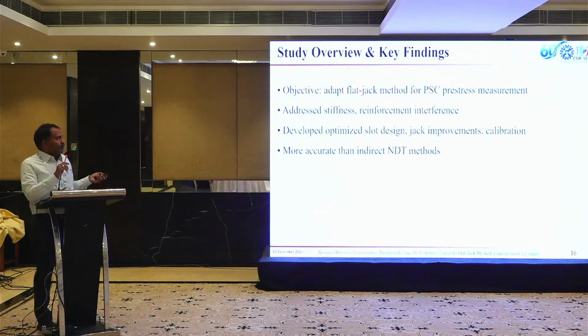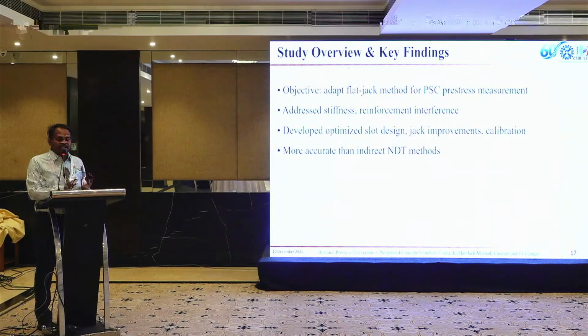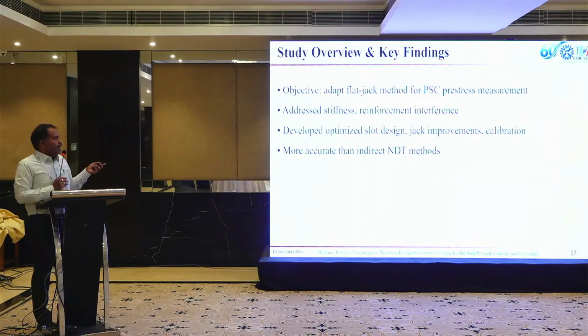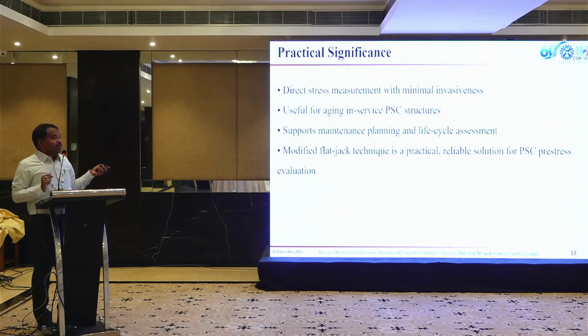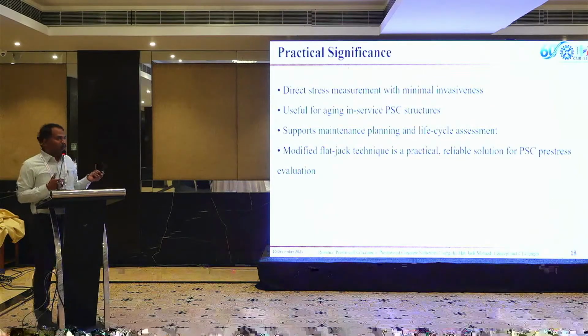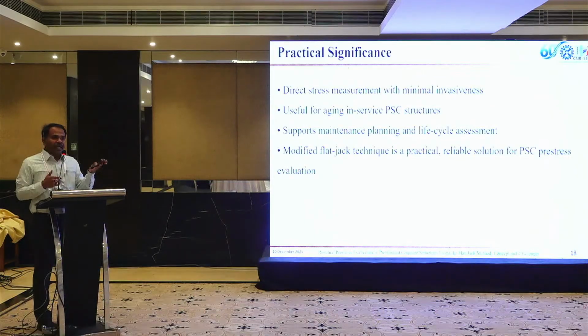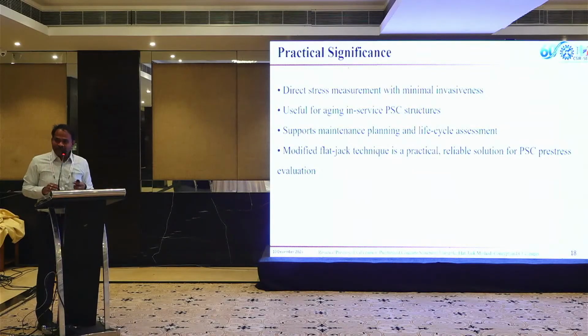The overview finding is adapting the flat jack method for pre-stressed concrete measurement. It will tell you the direct residual stresses in that concrete. Then it addresses stiffness and reinforcement interference by resizing or using new flat jack dimensions, and is more accurate than any NDT methods. This is direct stress measurement with minimal invasiveness, used for aiding in-service pre-stressed concrete structures.